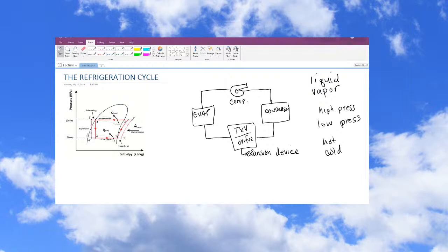Anyways, what we're doing is we're taking a refrigerant which has a low boiling temperature. Now that's really key. If you look at things like carbon dioxide or liquid nitrogen, those have very, very low boiling temperatures. And so when you put them in contact with something above that, what do you get? You get a phase change. If I take liquid nitrogen and pour it into the atmosphere, which is warm and at a low pressure, that liquid becomes a vapor.